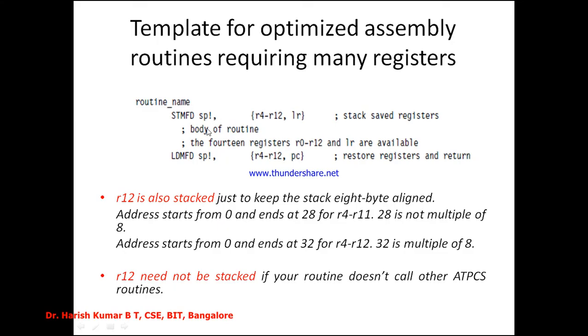If there is a need for you to use too many registers, and if the registers are not available, one simple technique is to use the stack. Store all the content of the registers there, then use those registers accordingly, as you need, and finally, once you have finished performing the computation, just restore the registers from the stack using the pop operation. LDM is loading all these registers from the stack.